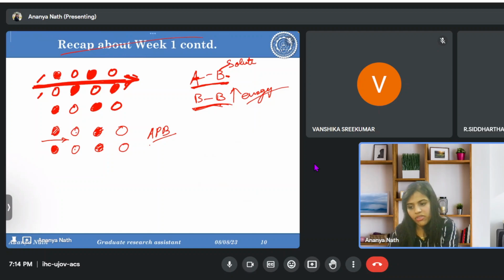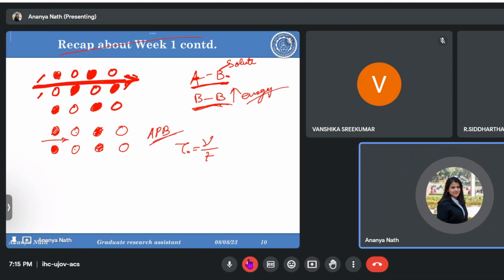And also there was a formula of tau, where tau was defined as the stress acting between the dislocation where it is finding difficulty to move further. Gamma is the antiphase boundary energy and T is the spacing. Antiphase boundary energy is higher in this case, and this is why the stress needed to move the dislocation is higher, and this is why the dislocation needs to break a lot more barriers in this case.